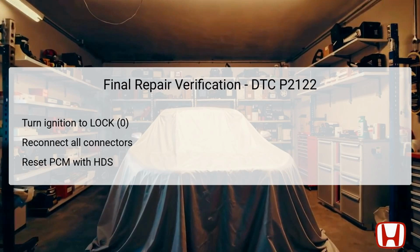The final stage of repair verification entails turning the ignition switch back to lock 0 for safety. Ensure all connectors are securely reconnected in their appropriate locations to maintain system integrity. Following this, reset the PCM using the HDS approach, which clears any stored fault codes and resets operational parameters.